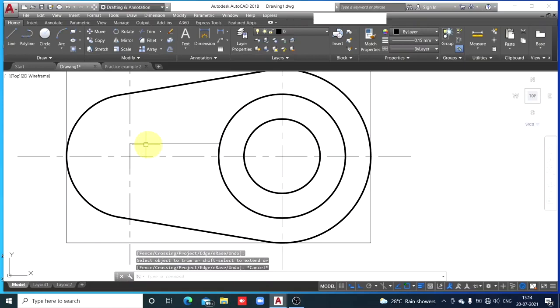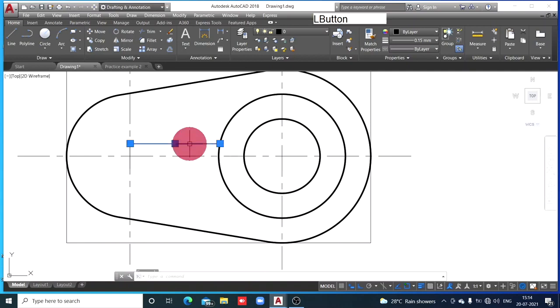So this is that strip up to the boundary of the cylinder. Now the same line I want to repeat here below the center line also at a distance of 5 millimeters. So I'll use the offset command. Watch here. Click offset. At a distance of 10 millimeters you want to offset it. So that 10 millimeter distance appears there in the command box.